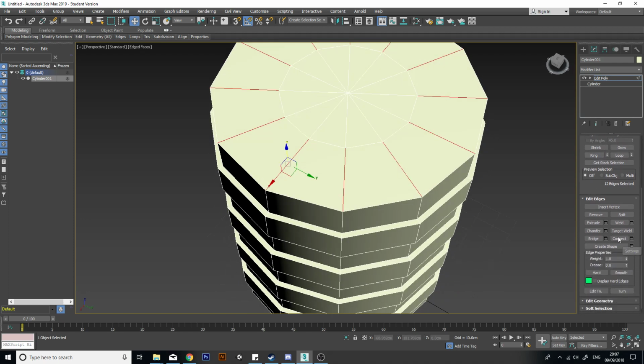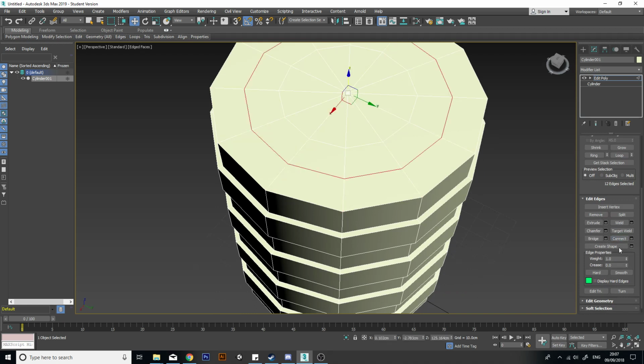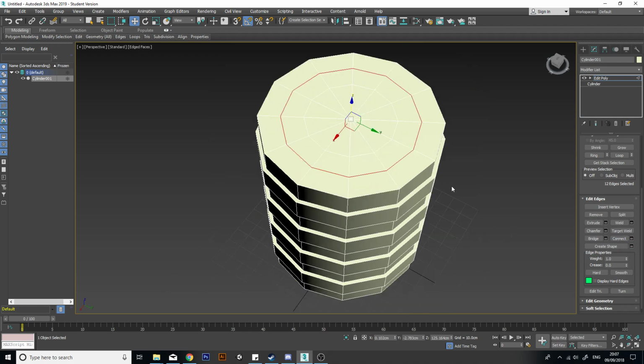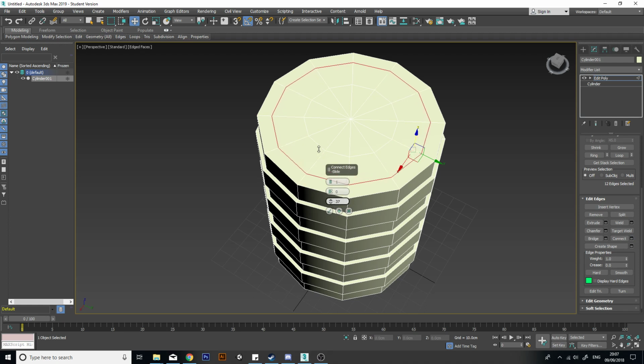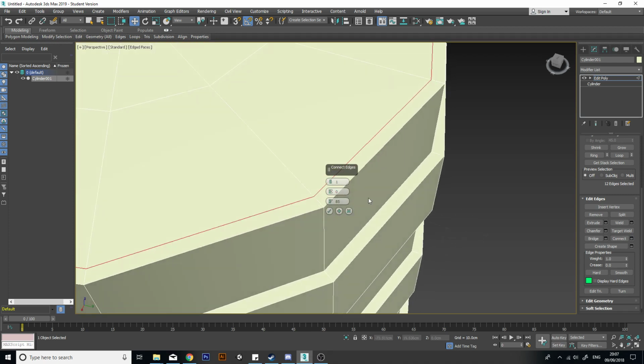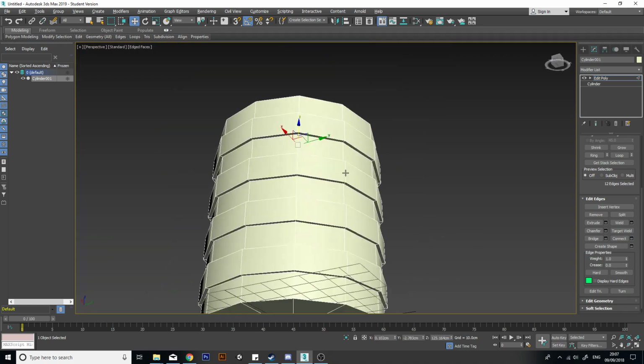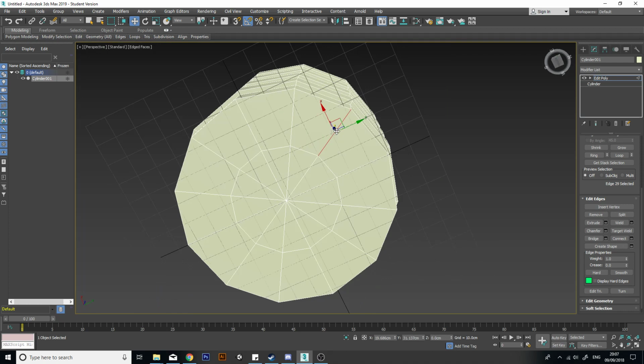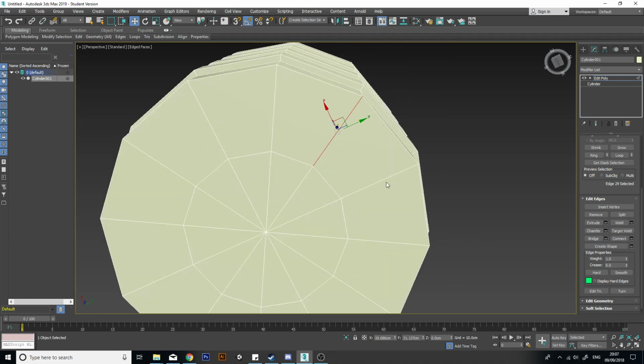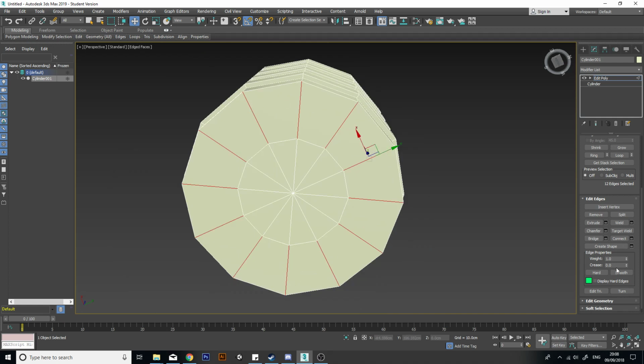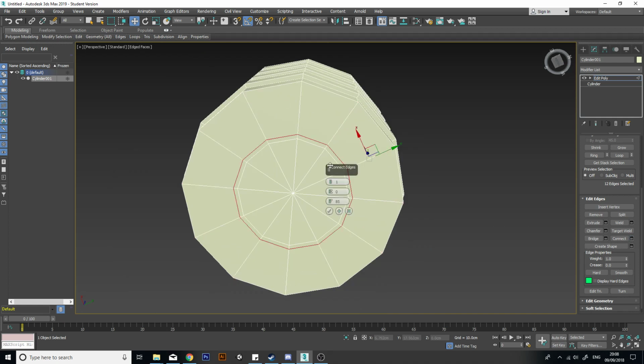and click connect. The reason why we're using these small dialog boxes instead of directly clicking connect is because you want some control over how we're doing it. For example, we want to slide this all the way to 85. Good. And we're going to do the same on the bottom here. Just press G to get rid of the grid. So we're going to press that and shift click. And now you see it's actually the wrong side. So here we have to go minus 85.